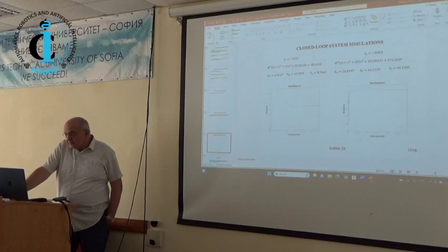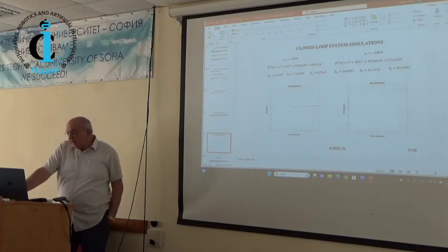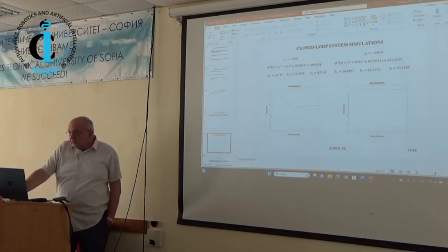So what I observed is that the settling time almost doesn't change, almost no change. The only change is with respect to the percentage overshoot. Nevertheless, the percentage overshoot decreases when I move the third pole to the left, but very slowly, by a small amount. Then finally, with that value of the third pole of the system, I got this step response.